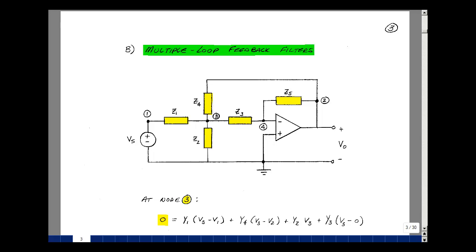You can see here, this particular structure we're going to analyze in just a minute has got an inverting amplifier here. Now with just R's and C's in these 2 impedances, you can only get real roots. We'll show why that's true in ECE 402. By adding a second feedback path, it's possible to create complex conjugate roots, which is what we need for this second order filter. Let's see if we can analyze this circuit in terms of the impedances, and then figure out what kind of components we need to put in these boxes to make this particular case a bandpass filter.